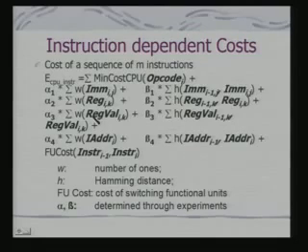Now what is the significance of these other terms? If you look into it, these count the number of ones, but it doesn't matter where the one is located; it counts the number of ones corresponding to these operands which will be part of the instruction. And this gives you the Hamming cost, that is, the Hamming distance, which is the number of differences in the corresponding bit positions of these operands, that is I minus 1 and I. So basically between the previous one and the current one.